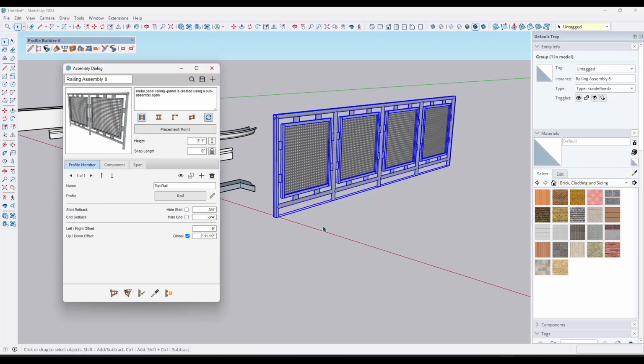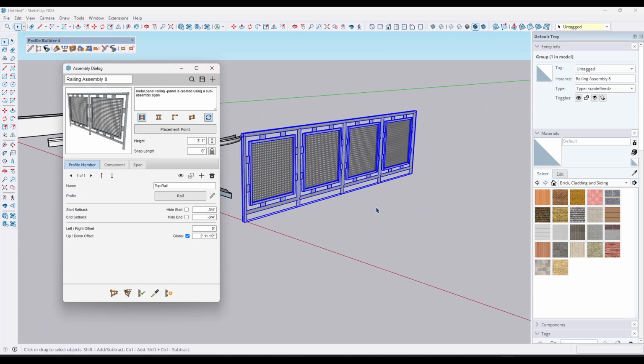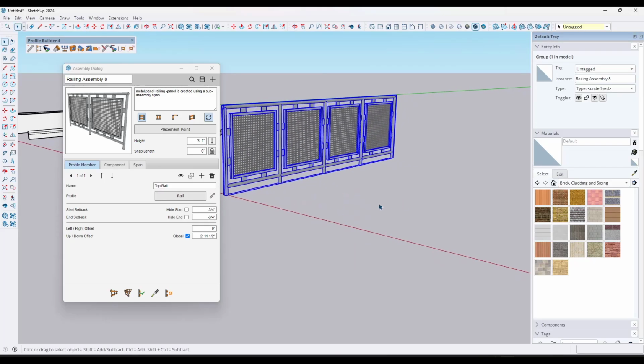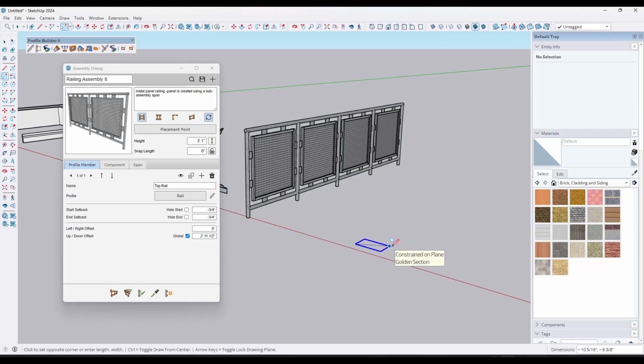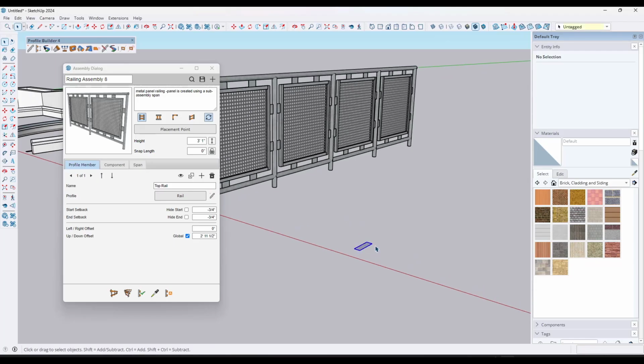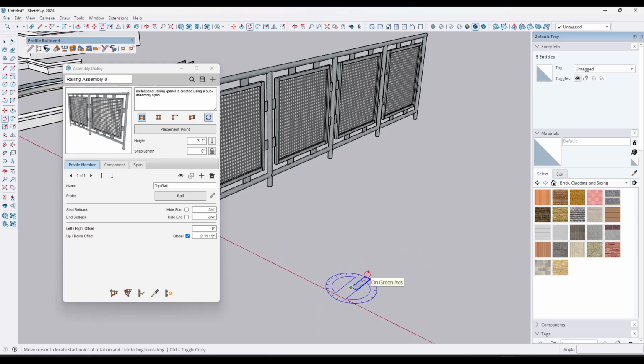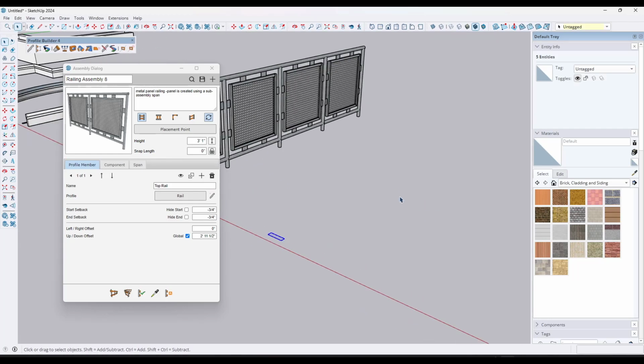So what you do is you combine things that are extruded with things that are repeated in order to create these profiles. Just as a quick example, let's say that we wanted to create a wall with framing. I'm just going to draw a rectangle right here, and we'll do an in-depth video about creating assemblies, so don't worry too much about that for right now. I'm going to create a 1.5 by 5.5 rectangle right here, and I'm going to rotate that like this.